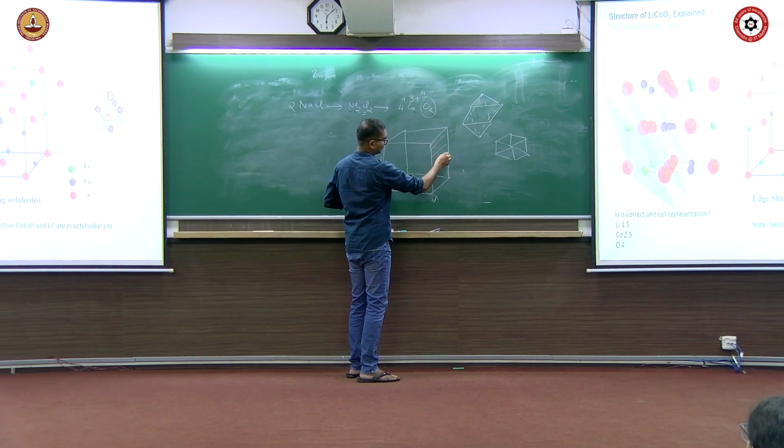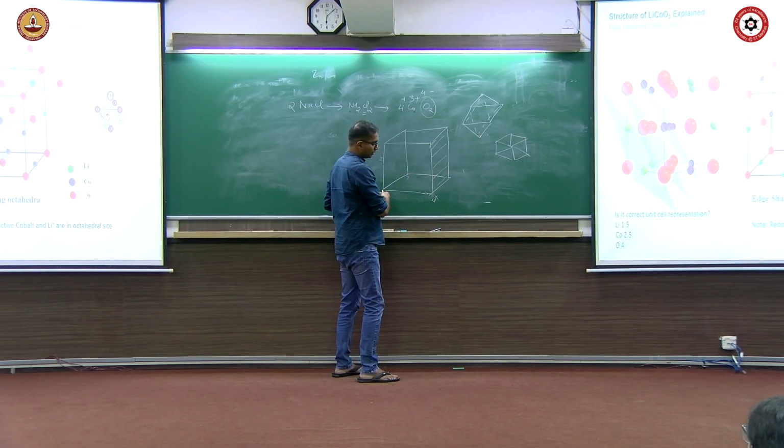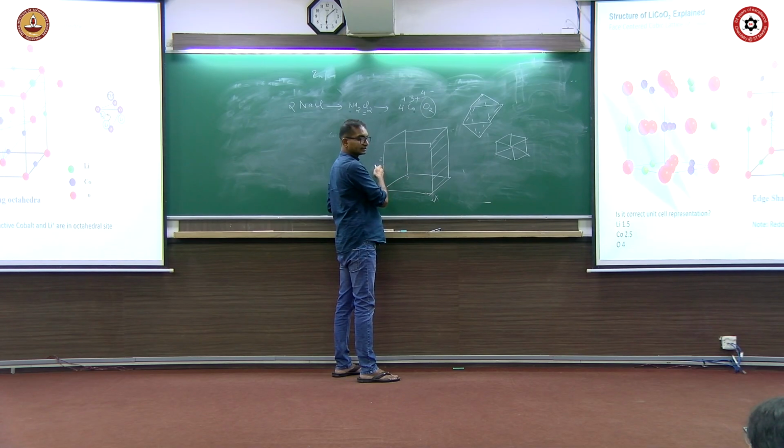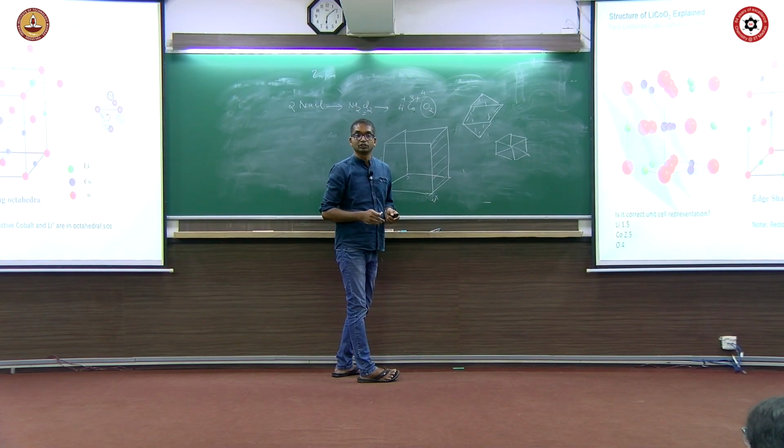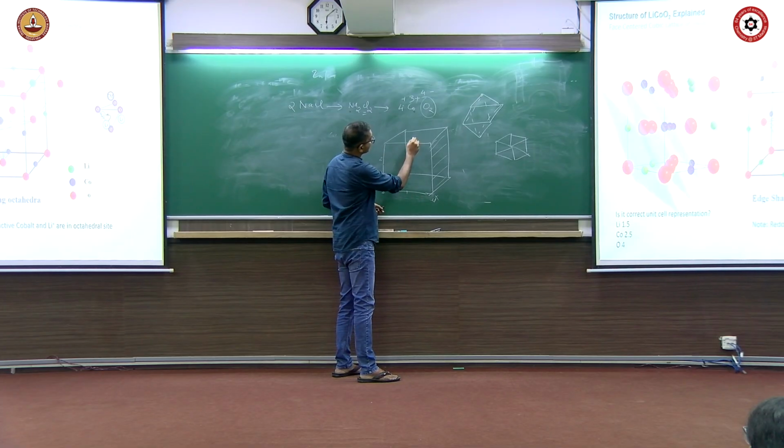This is that plane, right? I went 1 unit along the x-axis, parallel to y and z axis. So this will be parallel to that fellow. It will not be disturbed. Then that plane will be 1 0 0 plane. 1 0 0, right? If I am in the midway, suppose take midway.